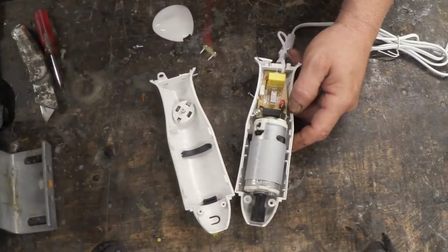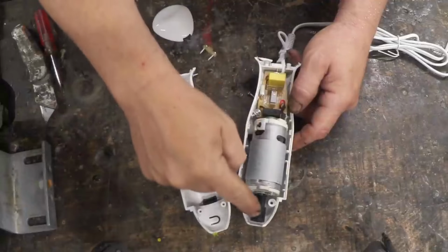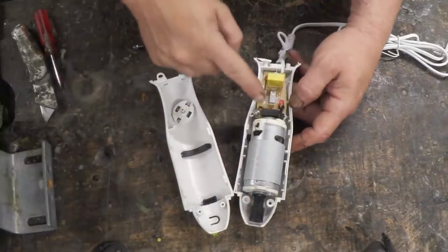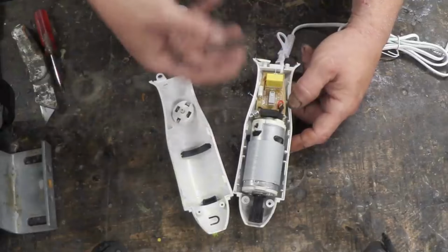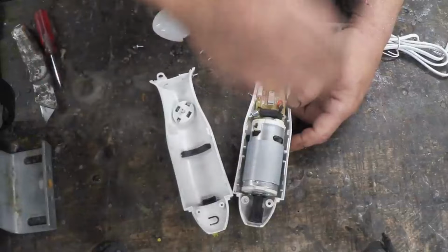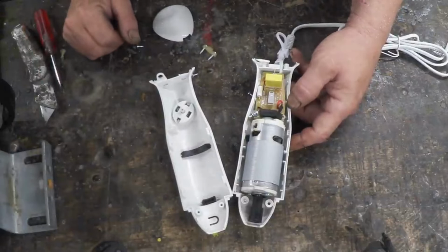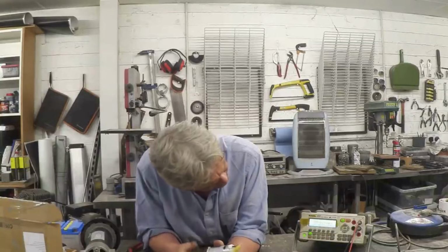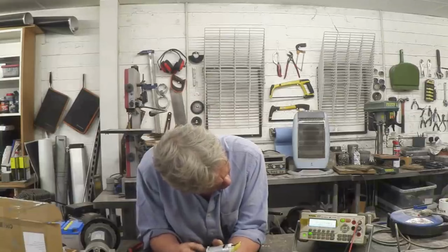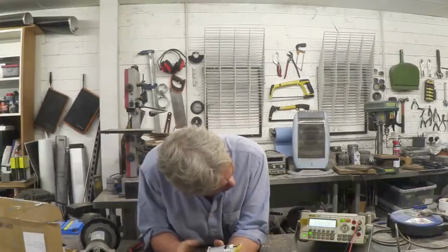So 4 screws, 2 at the top, 2 at the bottom, took this to pieces. And there's the motor's little drive spindle there to connect to the chopping blade. Here's our circuit board, that's a bridge rectifier, and then we've got our input. So we get a bridge rectifier, a switch, a whole load of cable, and this beautiful motor, all for £5.50. It just astonishes me. Anyway, that motor just lifts out. Okay, I've got the motor out, there's the meter. Now, given that this is about 10,000 RPM at 230 volts, we can expect quite a voltage on that when we spin it, so let's have a look. Look at that. Spinning it the wrong way for a start.